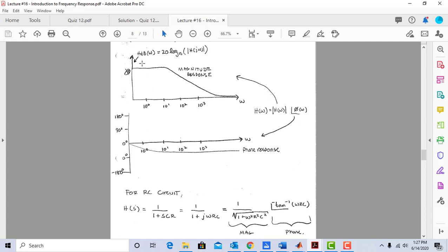So if I'm doing a magnitude response or a phase response, what I really want to do is say, I'd like, let's say, 10 points per tick here. That way, I'm going to have 10 nice little uniformly spaced frequency points between each of my divisions.